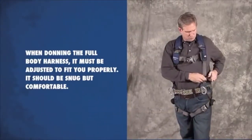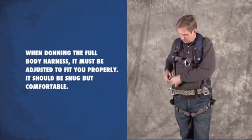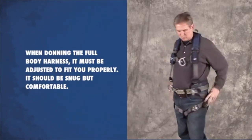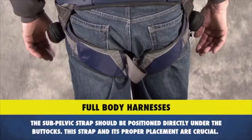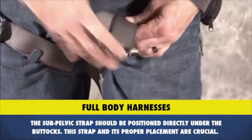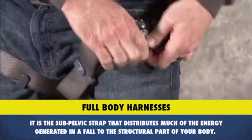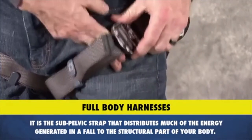When donning the full body harness, it must be adjusted to fit you properly. It should be snug, but comfortable. The sub-pelvic strap should be positioned directly under the buttocks. This strap and its proper placement are crucial. It is the sub-pelvic strap that distributes much of the energy generated in a fall to the structural part of your body.